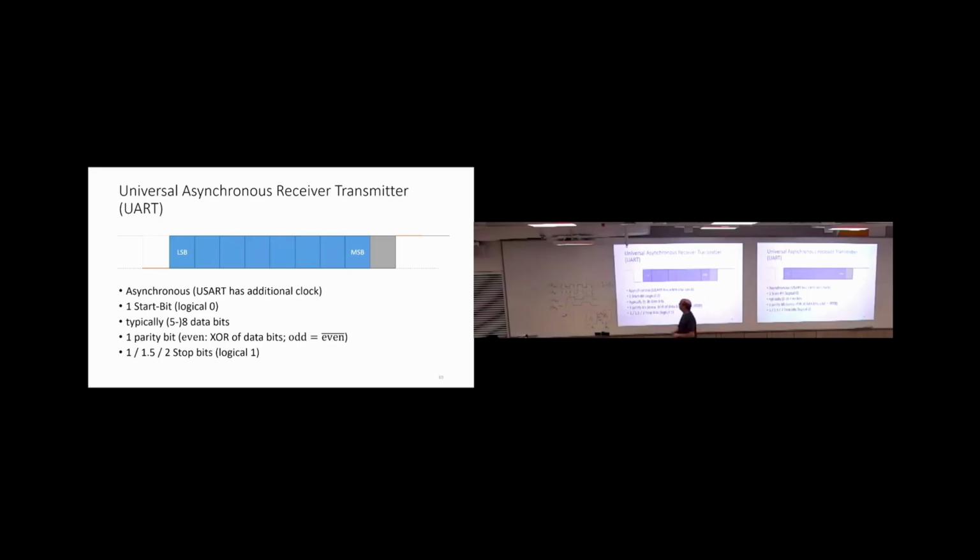So meaning, if I want to sample something with 1 microsecond length, I should sample with at least 500 nanoseconds. Why? Because in the worst case, I have one in the corner and one in the middle, right? That is the minimum. That is not sufficient for reliable data receival.